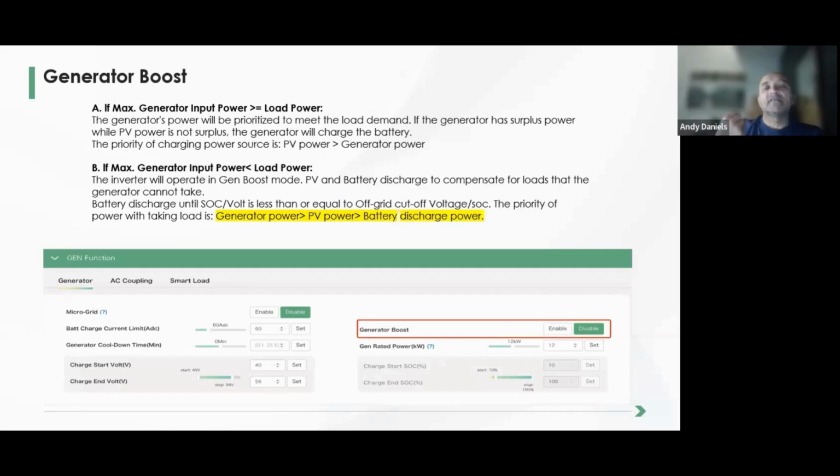Number one, it can give us an accurate indication of how much power is coming from the generator. But the second feature is a safety feature, and it means that we can now use solar to supply power to the loads without exporting power to the generator. As we know, that could be dangerous for the generator. So from the time that we added the CT onto the main board where the gen comes in, we've been able to have this gen boost function.